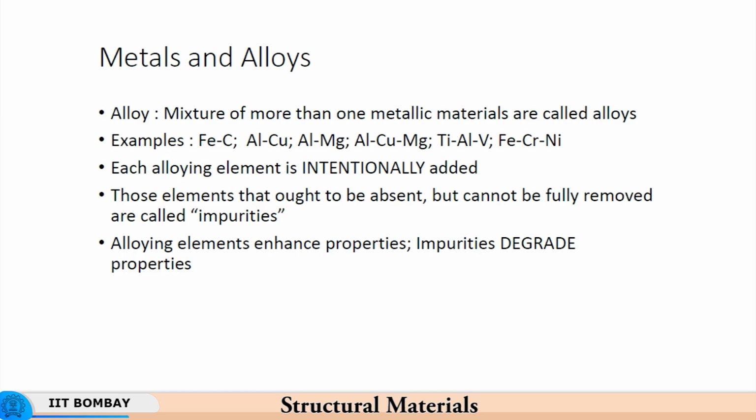We have aluminum magnesium alloys being used for auto bodies, or basically bodies of the vehicles, skin panels as it is called. These are expensive because aluminum is expensive, but then these are much lighter as compared to steel. So, if you want to make a very lightweight vehicle which will consume much less fuel, highly fuel efficient vehicles, in that case one would use aluminum magnesium alloys, and these have been used very successfully in many of these commercial vehicles produced.